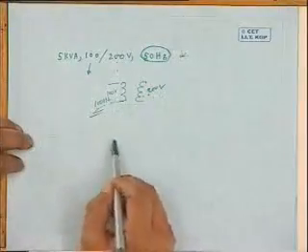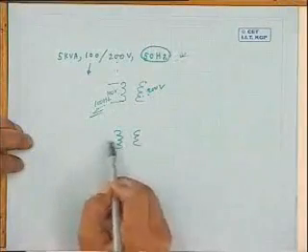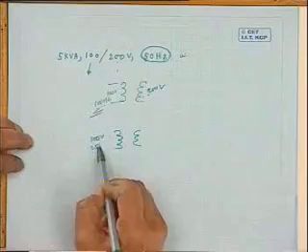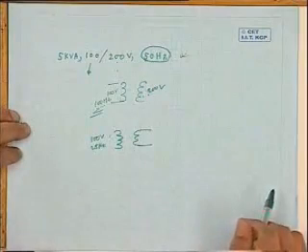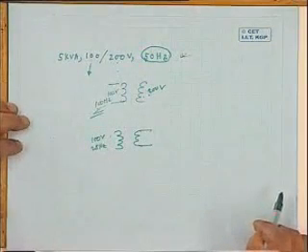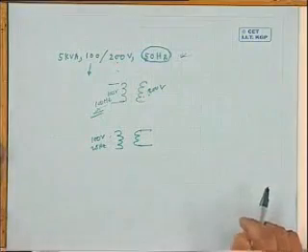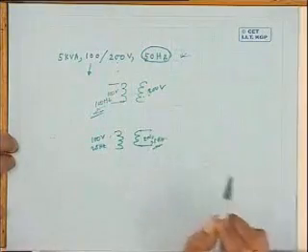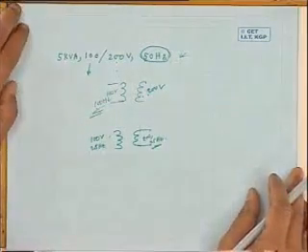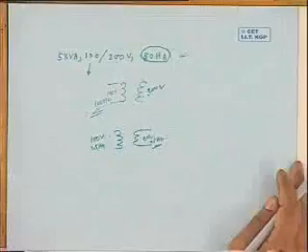But my next question is, suppose this 100 volt, 200 volt transformer, I energize the primary with 100 volt, 25 hertz, a lower frequency. What will be the secondary voltage and its frequency? 200 volt, 25 hertz, at least theoretically it should be like that. But the important point is, at low frequency, if you give supply, something else will also happen. That point I want to highlight in whatever time is left today.